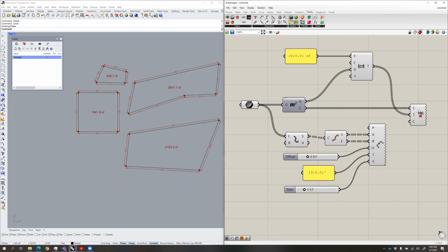Another thing you can do is if you want to turn off a component, let's say you want to take this area here, and just disable preview. If you select it and right click anywhere in Grasshopper, you can choose this preview off button, the thing that looks like a guy with a blindfold, looks like he's a hostage. Click on the hostage and that turns off the label, but it's still running in the background. So if you click on anything that's grayed like this, and then turn on the kidnapper, there it is, and it's revealed once again.